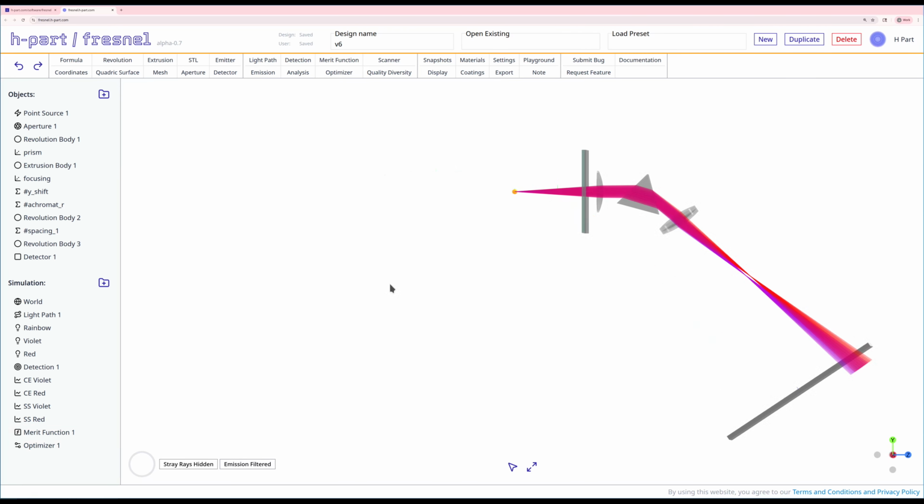All right, so now that we've set up the achromat and configured the light path, we're going to reset some of the tilt and other configurations that we did during the first series of optimizations. And I'm also going to remove those parameters from the merit function to simplify the optimization and make it more likely that we get to a good place before we allow the tilt and rotation to fine-tune it.